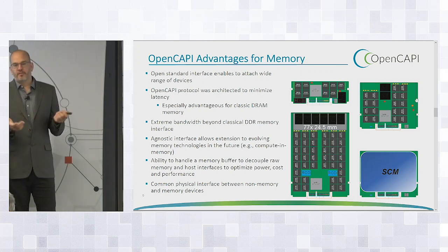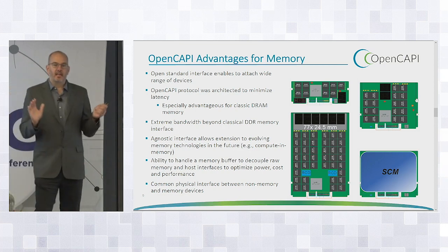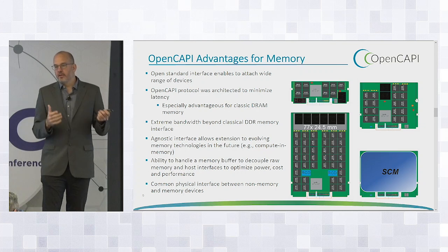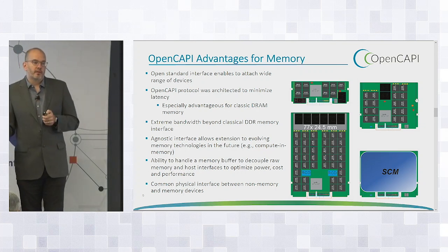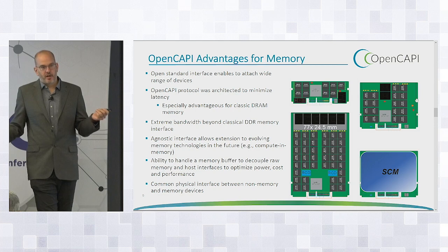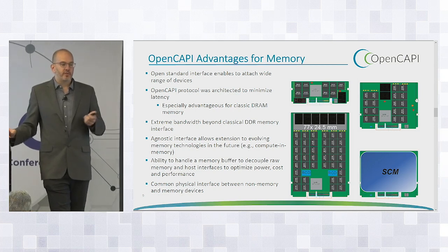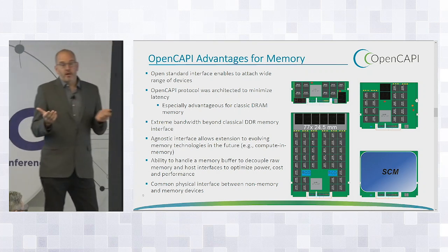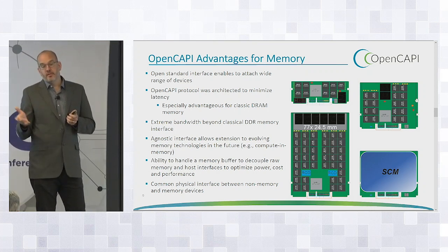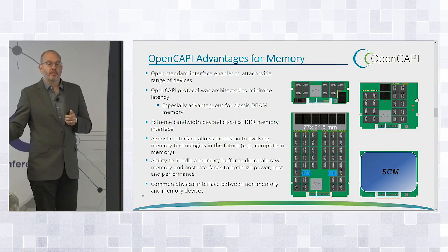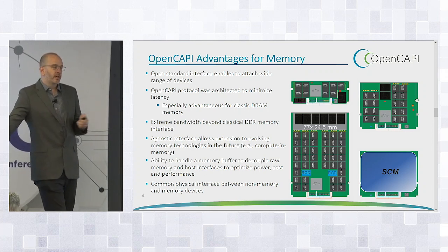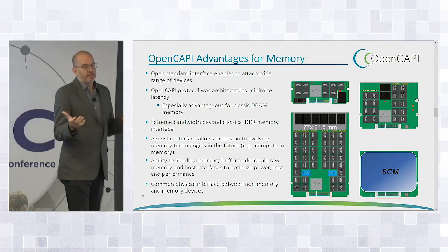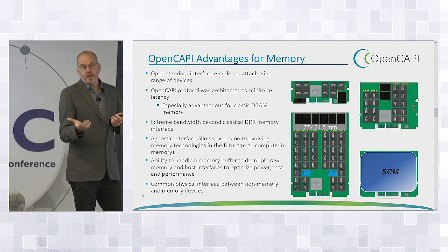Now I have to come up with, I'm going to call it, a slightly hacky approach to try and integrate different memory latencies into this very bare DDR protocol. And so the DDR protocol has big problems. It's too slow, and it's too tied to the device media. So what we want to do is run it on differential signaling, just like every other interface in the processor has moved to, other than memory. What this differential signaling gives you is a massive increase in bandwidth. And it also enables you to develop a protocol that's memory agnostic.